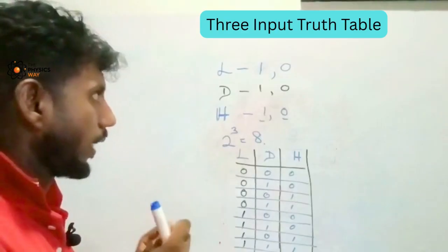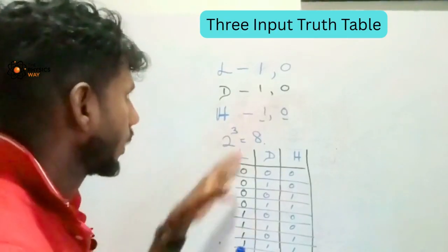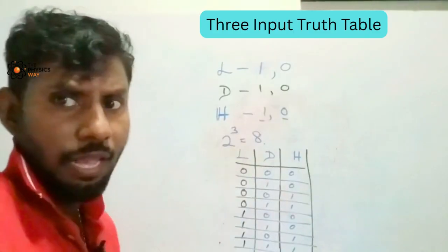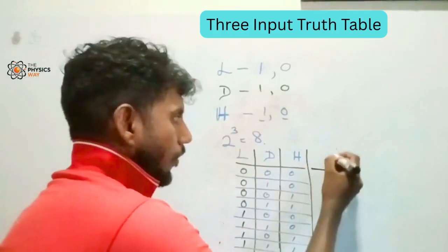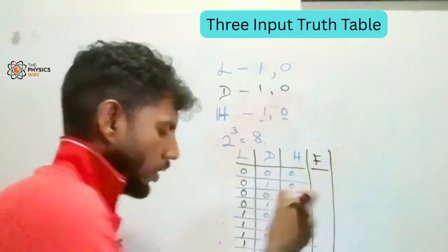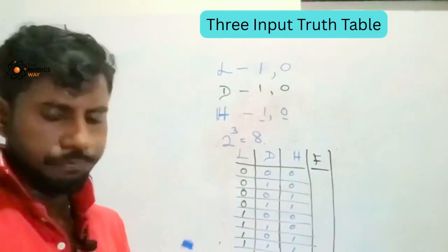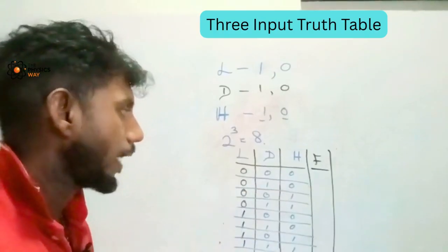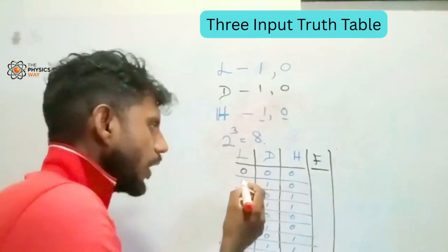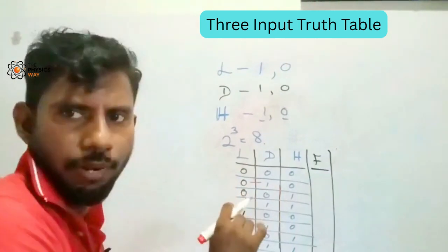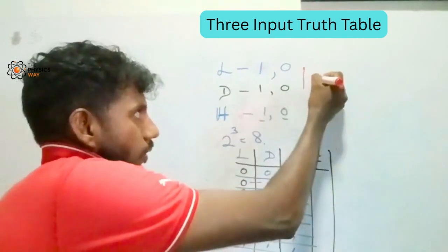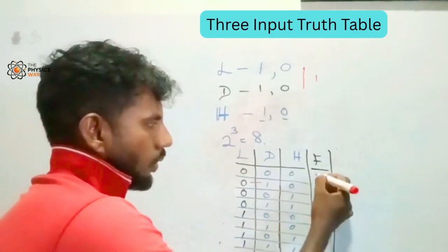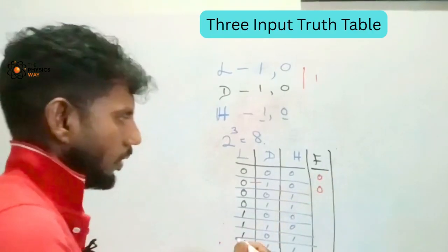So now let's look at the conditions they are asking from us, right? All goes 0. I mean, we don't need the fan, right? If the fan is F, we don't need the fan. And yes, the door is closed, but the machine is not operating. These two both have to be 1, otherwise the fan will not work, right? So again, no humidity sensor, so again here 0 0.